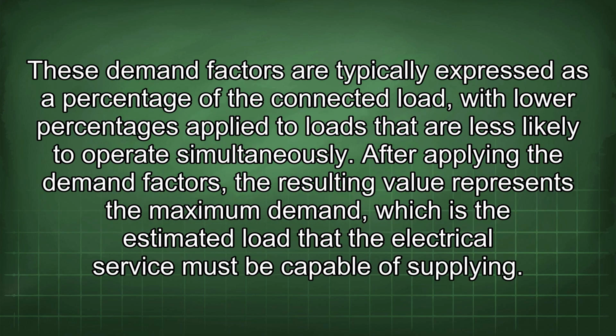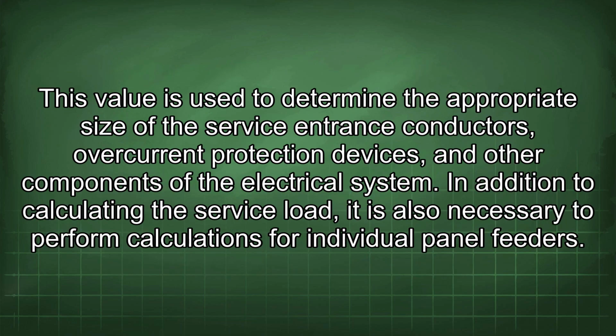These demand factors are typically expressed as a percentage of the connected load, with lower percentages applied to loads that are less likely to operate simultaneously. After applying the demand factors, the resulting value represents the maximum demand, which is the estimated load that the electrical service must be capable of supplying. This value is used to determine the appropriate size of the service entrance conductors, overcurrent protection devices, and other components of the electrical system.